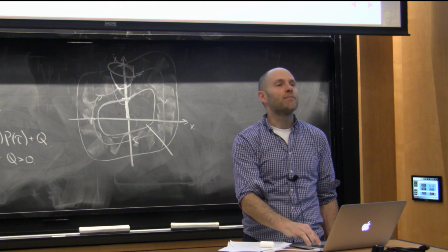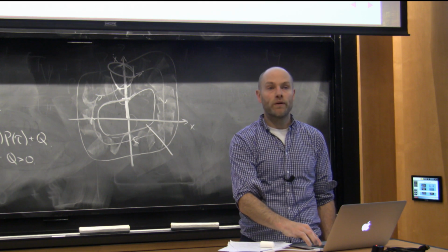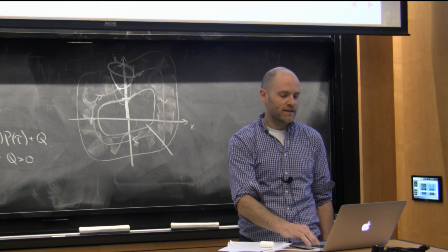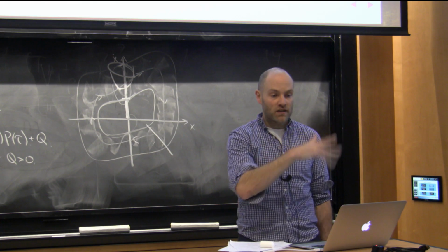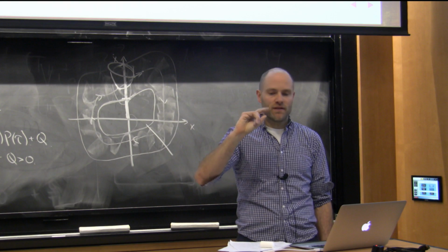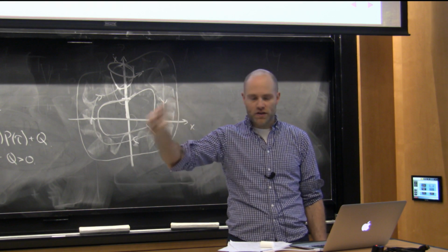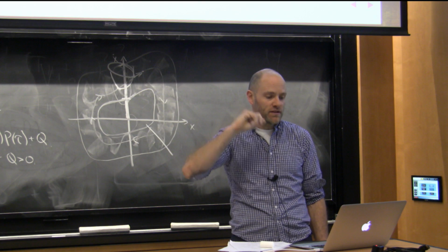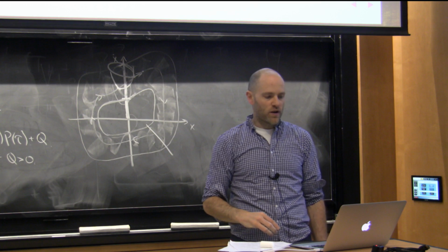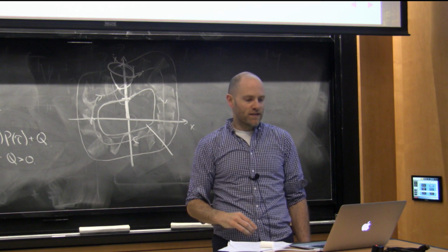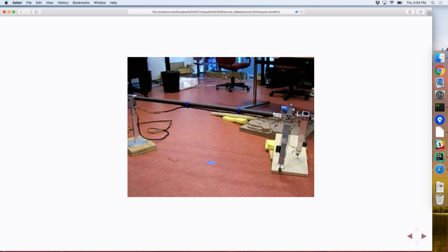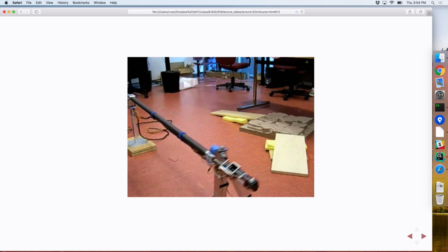So we built a series of these compass gait walkers where we did trajectory optimization to design the nominal limit cycles and the nominal gaits. We did a transverse linearization to stabilize those limit cycles, to design a control input that varied over the period, or over the trajectory, to give long-term orbital stability. And we even did the region of attraction analysis like you saw. We had a series of walking robots that would fool around in the lab, and that was an earlier one before Zach built a cool big one.